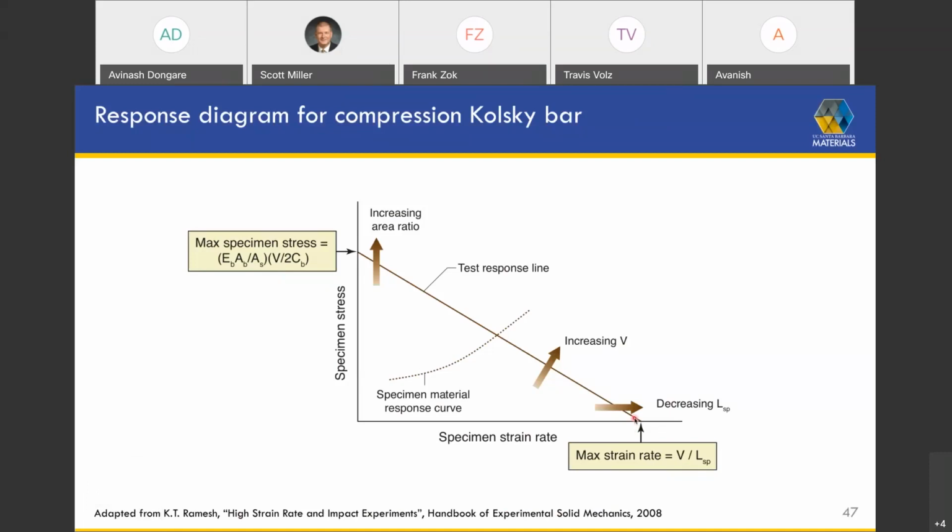But you find that because the material is weak or soft, the magnitude of the strains that reflect that strength, think of this as the strain in the transmission bar, those strains will be very small. Those are the strains that reflect the back face stresses. So if those strains get to be very small, you have problems with signal to noise ratio. And so you start to lose on the fidelity of the measurements.